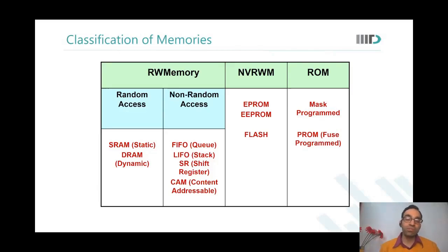In fact, if it so happens that you are very clear about what your boot sequence would be throughout the life cycle of the product, you would not even use an EPROM. EPROM is less dense than a ROM. So you would instead use a mask programmed ROM. It is much denser. But typically we understand that system upgrade may happen, or tomorrow I may want to add